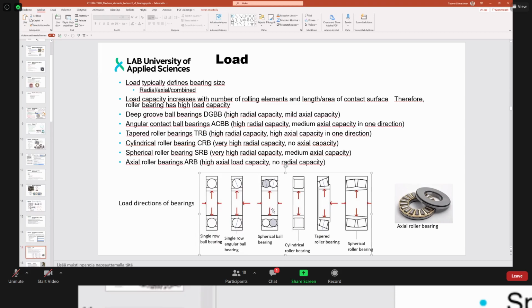And could you imagine what would be the benefit of this kind of bearing system? Maybe less load on the outer ring. Yeah, perhaps yes, also. But think about movement. If you think, for example, of shaft deflection, what would happen in this kind of bearing if the shaft is deflecting a lot, compared to the single row? This bearing will allow movement of the shaft?